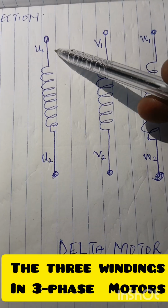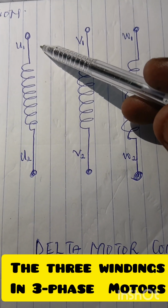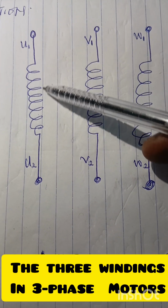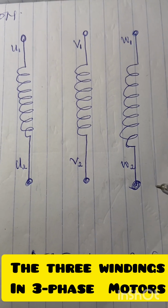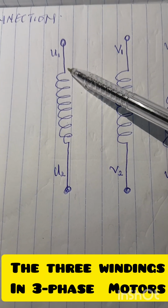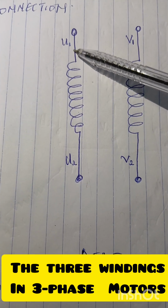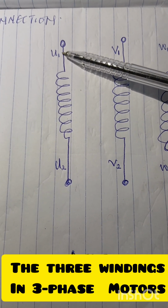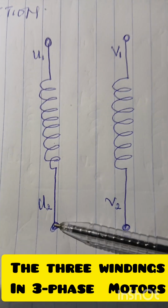This coil here is the first coil, which means a three-phase motor has three sets of coils. We'll call them coil U, coil V, and coil W. Coil U has the start and the end, and that is why we label it as U1 and U2. The start of coil U is U1 and the end is U2.